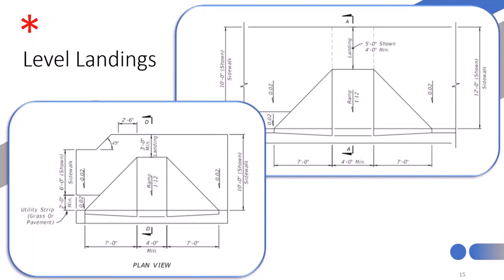But a lot of times we see situations where the curb ramp's location, if it's included in the scope of the project, could actually be shifted a little bit further up station or down station, and then that full 5 foot desired or standard landing width could be achieved.